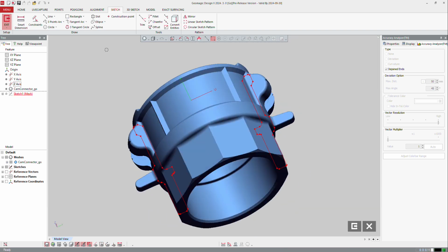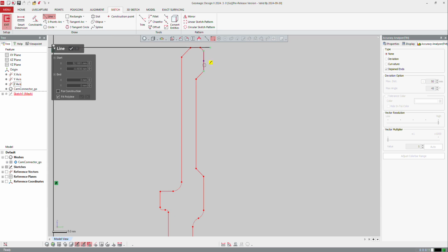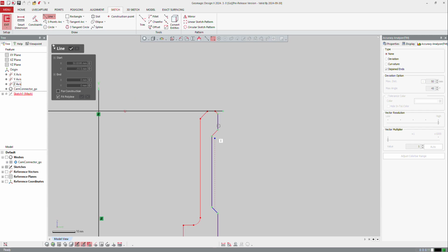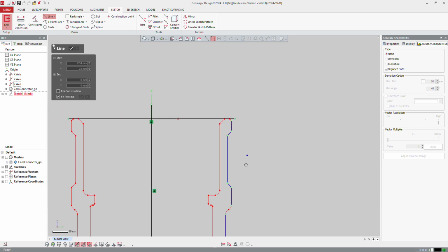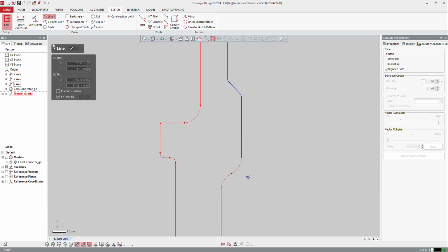Okay. Now I will create my sketch, but first of all, I can retrieve the Y axis and the Z axis, as this is a revolution axis, and these can be used on the part. From that, I will now build my sketch, so I can double click here, double click there, and create all my curves or lines on the part. Right now I create lines. Then, don't forget, I can create extra lines like that one between the two fillets. There is no line, so I will create that line.